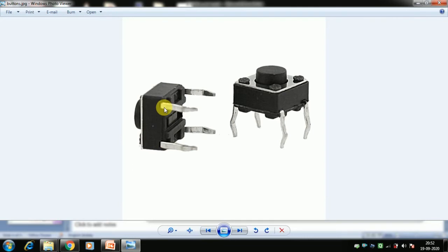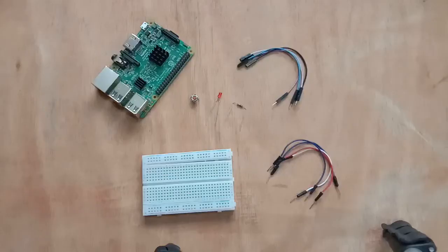And when we go and build the circuit on the breadboard, please mind, I made one mistake there. All the circuitry should be in line on the breadboard with this pin. I missed this pin by one row, so I put all my jumper wires in the row beside. When you do it, just do it correctly. Put it in the same row where this button pin is. Okay. Let us now do the circuit.